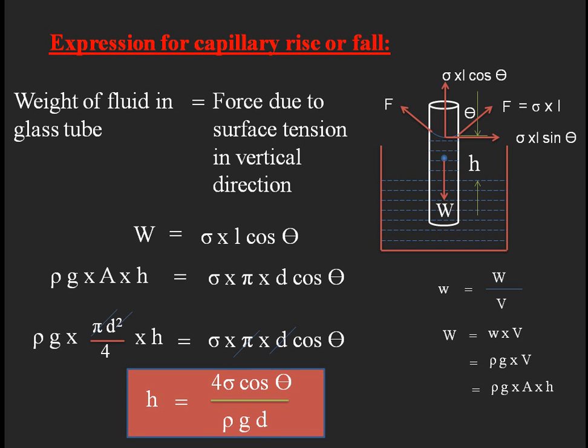Okay, so this is the way of understanding capillary rise or capillary fall. Please try to remember the equation, that is the formula 4 sigma cos theta by rho g d, which is very important for your competitive examinations, in which they may ask what is the capillary rise or capillary fall, what is the equation we can write. So please try to remember the equation.